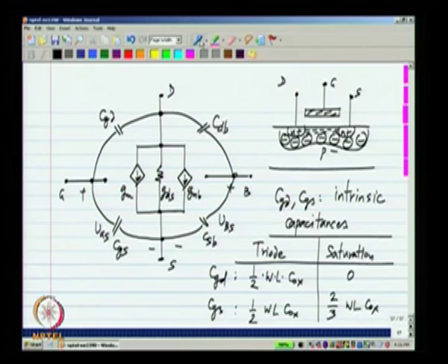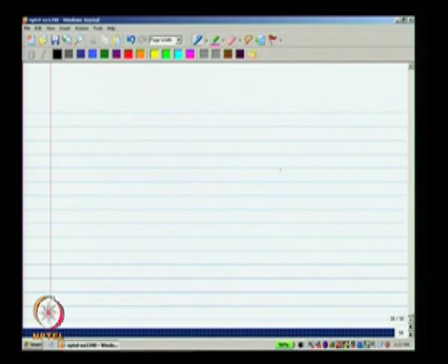In addition to this, you see that you have some conducting material here. In addition to this, you could also have these wires and you have the conducting gate, and between these two there will be a capacitance. This is not inherent to the operation of the MOSFET, but it is there simply because there are two pieces of conducting material close to each other. Okay. So, the actual CGD and CGS will consist of this plus some overlap capacitance and that plus some overlap capacitance. Okay. Now, again drawing the picture of the MOSFET.